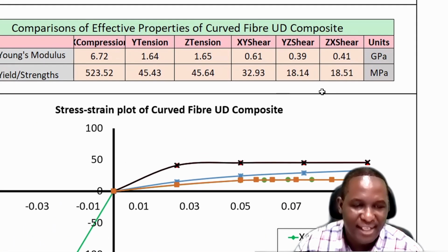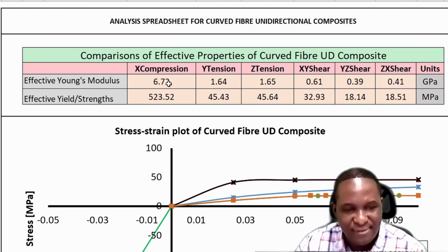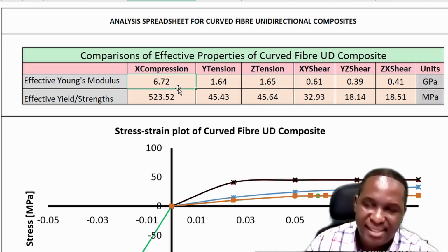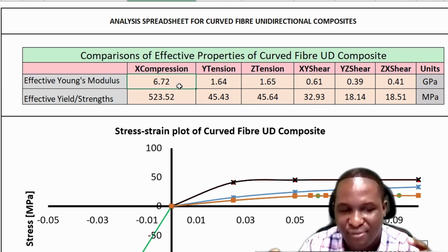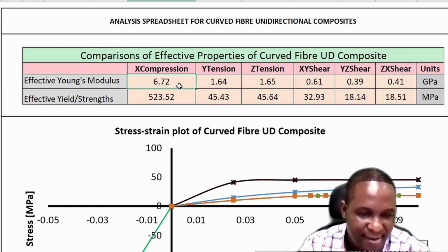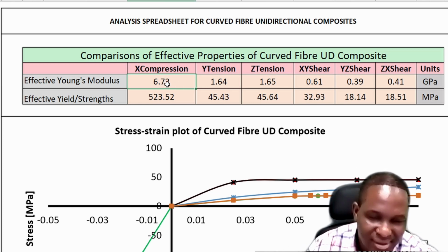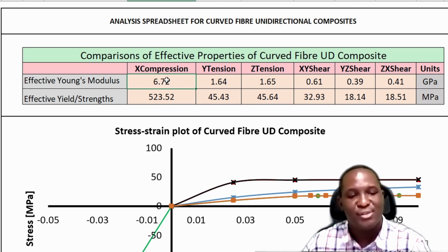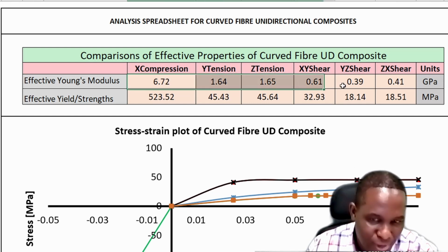So if you then go back finally and look at the values that we have here, you could see what's happening, the compressive case, the modulus, this is the fiber direction, the modulus is a lot. This, again, is a little bit less than what you would get if they were linear oriented values. So if you make a calculation on this kind of thing based on, let's say, linear arrangement of fibers, this number will probably be somewhere around 10, 12 using rule of mixture. So clearly the fiber orientation, the undular, the curved nature of the fiber is affecting the result across the board.